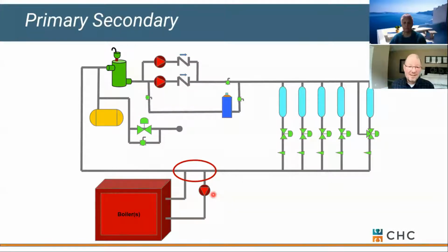That's your indicator. Before I leave this slide, a lot of guys ask, so what's considered closely spaced on our T's? How close do we want to get them? Well, 3 to 10 pipe diameters is a good rule of thumb. So it really depends on your line size, but then 3 to 10 is a good rule. If you get them too far apart, spaced a long distance apart, you're going to get some friction loss in here, and you may get some ghost flow that occurs in your boiler circuit when you don't want it. So having them closely spaced eliminates that potential.